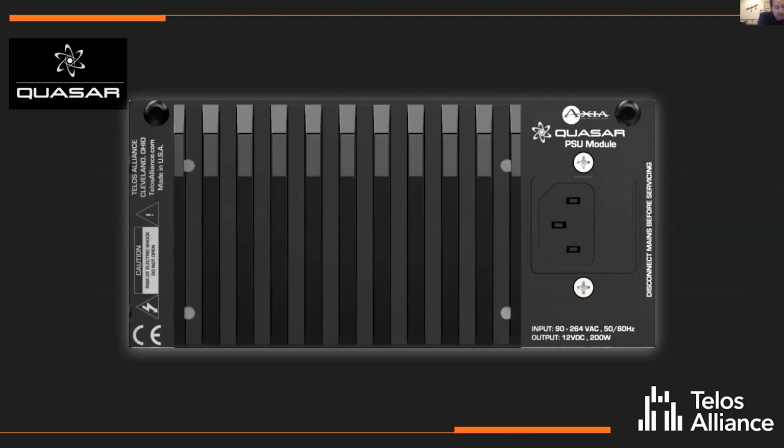The power supply is just a very robust switching load sharing power supply. That console can provide spaces, depending upon the size of the console, for up to 4 power supplies. So you can really have a high level of redundancy. Our biggest consoles, we recommend you run them on a minimum of 2 supplies, just because the current draw is enough that you don't want to be up in the 80-90% load range of a single power supply. So we do recommend that for the larger consoles, you power them with a minimum of 2 supplies. And in fact, when you order a frame, they come standard with those 2 supplies. And then power supply number 3 and 4 would be your redundant supplies.